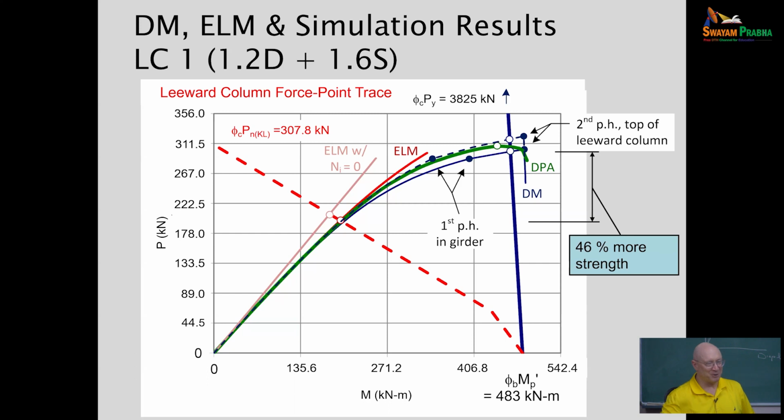So in the Americas, a reduced stiffness with a notional load, or an out-of-plumbness, that's more representative of what you would tolerate. In Europe, a larger notional load or a larger imperfection that's increased to try to capture the aspect that I'm going to get a larger bending effect as I start to approach a strength condition.